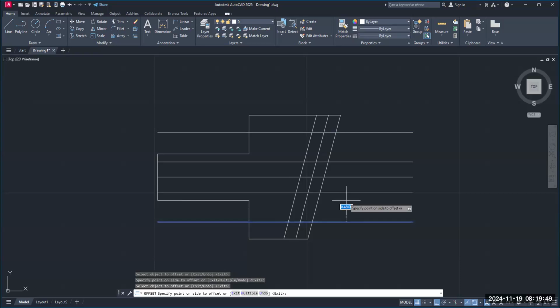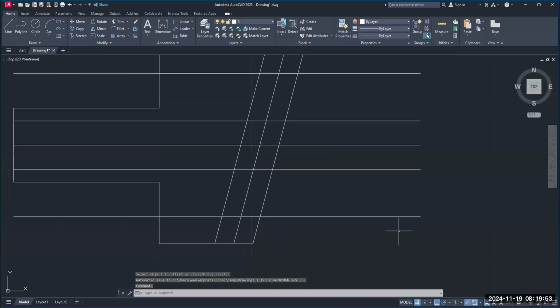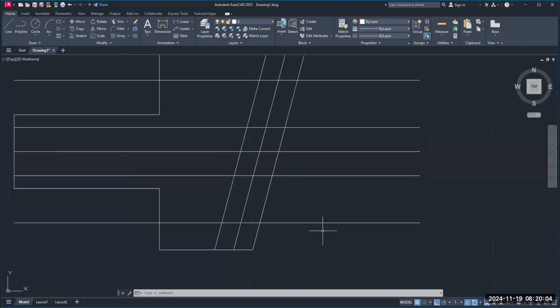Click, enter. All right, Mr. Morris, why'd you do all this? Well, I have an intersection right here. I want to put a threaded hole, one here and one here. Now, the thread size is a 10-32. Mr. Morris took it upon himself to go look up the tap drill size for these holes.